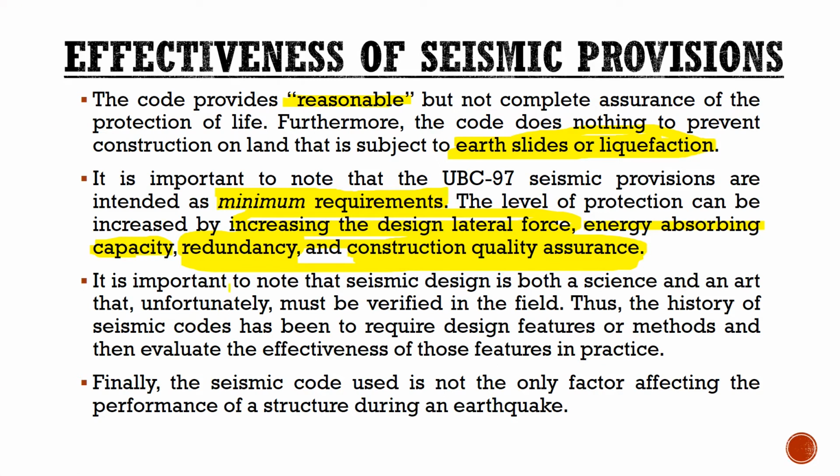Then it is important to note that seismic design is both a science and an art that unfortunately must be verified in the field. That is still the case, guys, so verification in the field. Thus, the history of seismic codes has been to require design features or methods and then evaluate the effects of these features in practice. Sometimes there are good provisions that are ambitious, but when you get to the actual construction it is difficult to execute. So you will see that later. So you have to evaluate.